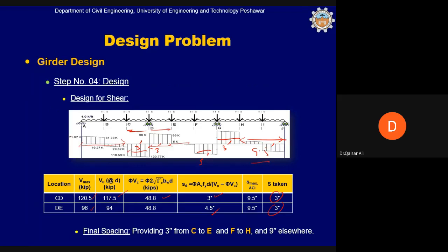So I will not keep on changing the stirrup spacing, and I will use only one spacing, because in this one girder, if we change the stirrups for economy, we will at the end only save 5 or 6 or 10 stirrups, which in the whole project possess no monetary value. This will not give us a big saving. But it will simplify our work and the work of the field supervisory staff.